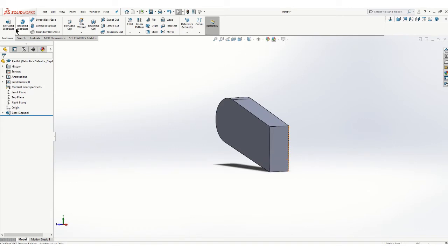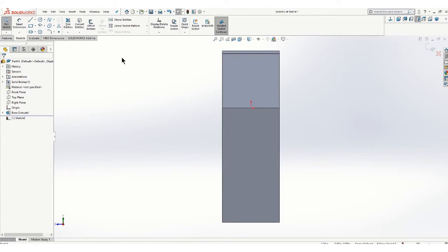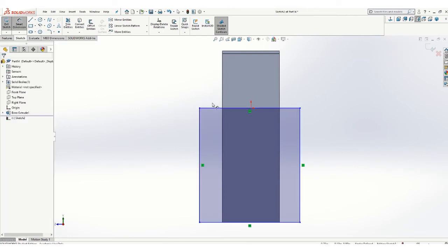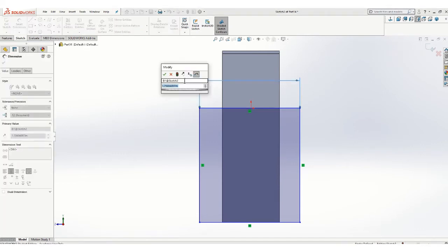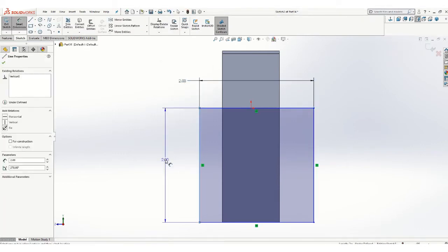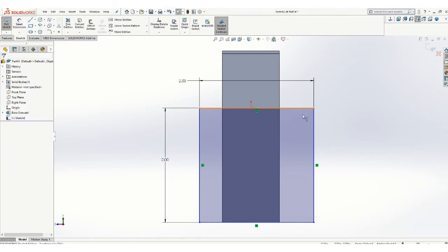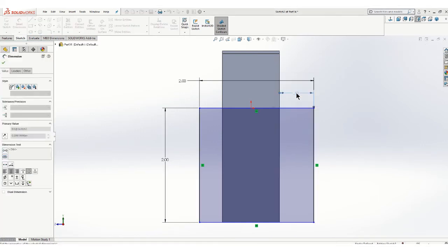And then we'll do a new sketch on the back of here. Use my rectangle tool, and that pad that's on the back is actually the same height, so I can line it up. Don't click it, but if you line it up like that, it'll try to lock onto there, and then we can add our dimensions. And it probably doesn't need that dimension. Oh, we need to do the side-to-side dimension. There to there, that should be 0.5.